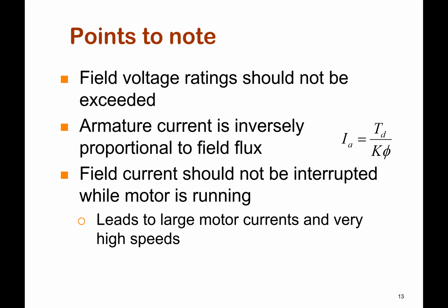So just to summarize again, you have to ensure that field voltage ratings are not exceeded, and make sure you do not exceed the ratings for the machine. One of the things you should also note is that we should not interrupt the field current, not the armature current, but the field current while the motor is running.